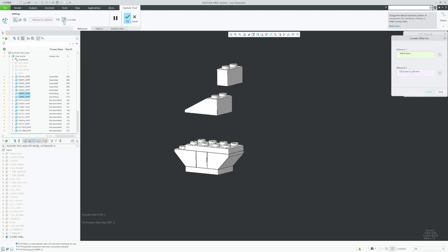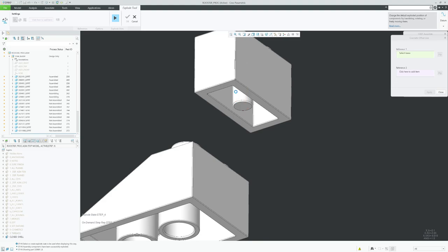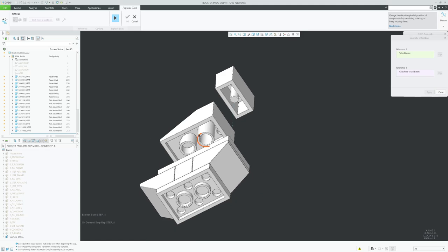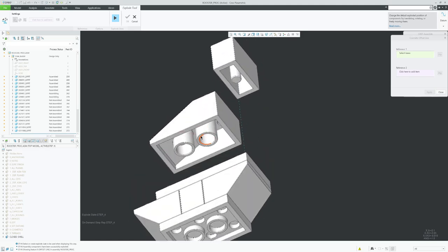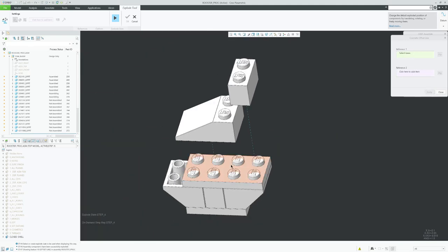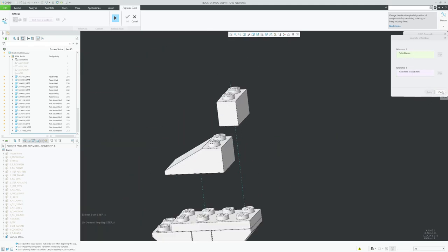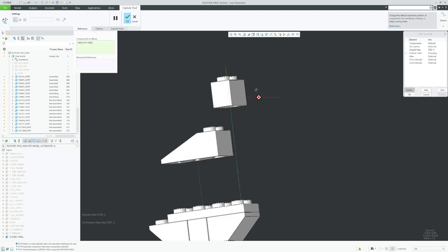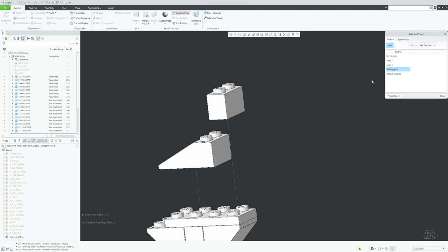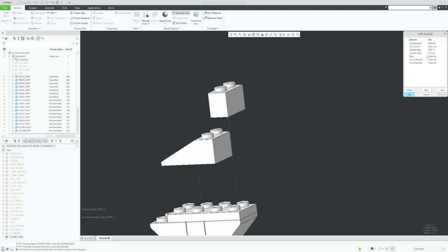move them up, magic wand, select this surface, this one, then it can be this surface right here, and then select this surface, click close, select this line that is outside of the component, click explode lines, edit, and move this line down like this. Click OK, right mouse button, save, OK, close, and OK.